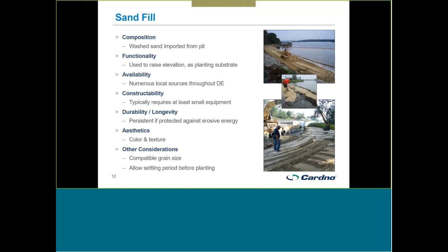In terms of its durability and longevity, it's very persistent if the wave energy is such that it will stay in place. And that's usually dictated by other components of your design, sometimes just your site conditions. But your site conditions in combination with other components of your living shoreline will help create this energy environment that will allow the sand to persist. Aesthetically, people like it. It looks kind of like a beach. It doesn't catch your eye as out of place on a shoreline.